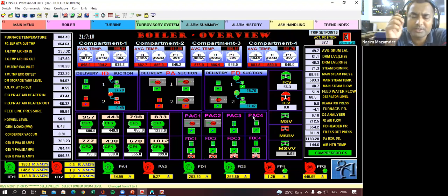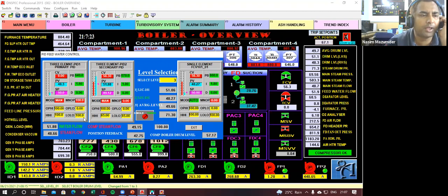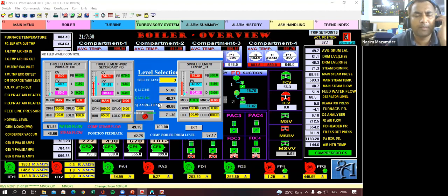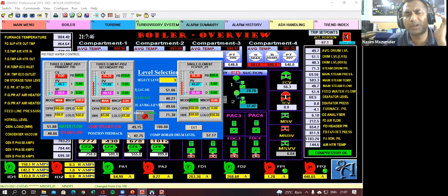If you know it is 4 to 20 milliampere, and it is an I2P, you first check on which channel it has been connected. Go to that particular channel. You give some command from your SCADA page. Suppose you give first a 0 command, and for that I can make this manual, and then I give a 0 command. Now what will happen? You must receive 4 milliampere on that particular channel. If it is 100, then you must get 20 milliampere on that channel.